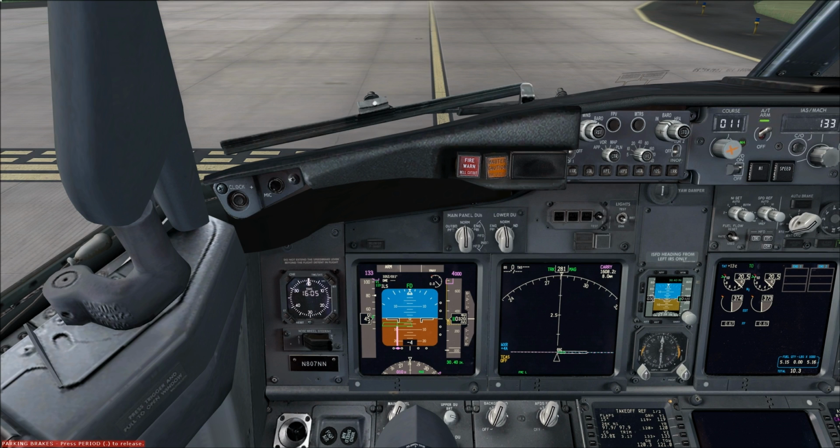If you are on the ground and let's say you're taxiing and wind shear is detected by the PWS, then it is recommended that you delay the takeoff for no less than 10 minutes after the wind shear was last detected, if in your judgment as captain that it will be in your flight path.